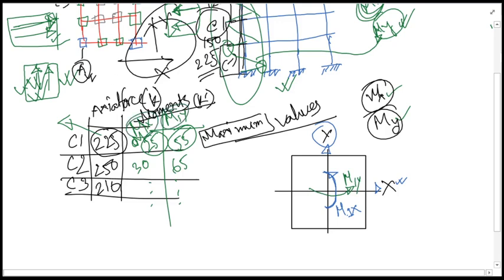The axial force is not acting on this point, rather it might be acting on this point with some eccentricities, which will give you some Ex and Ey values.